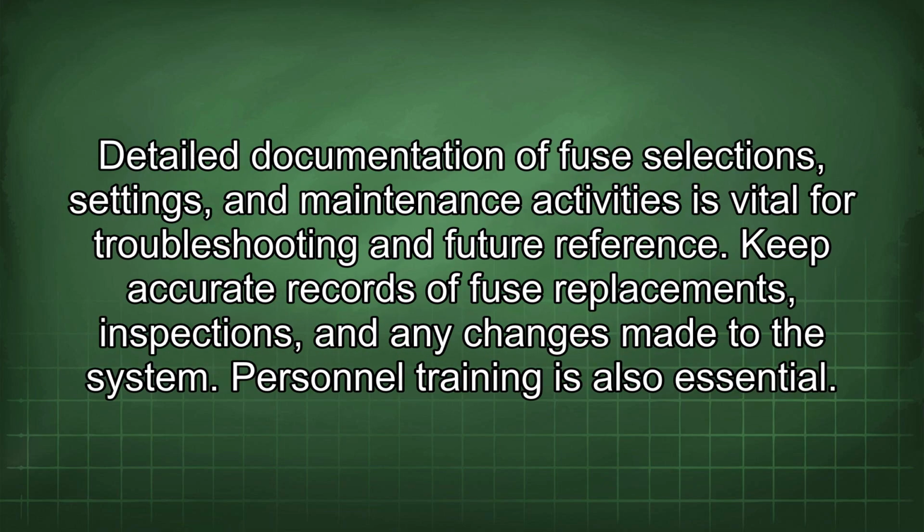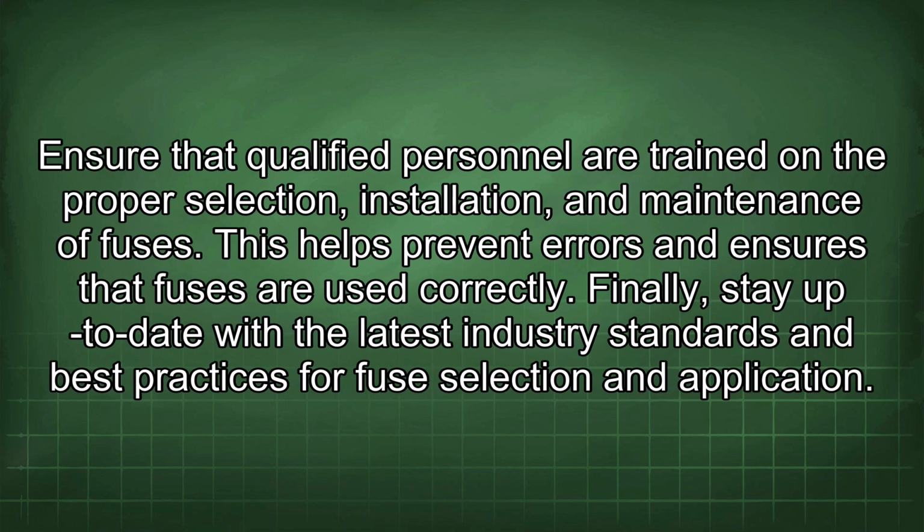Detailed documentation of fuse selections, settings, and maintenance activities is vital for troubleshooting and future reference. Keep accurate records of fuse replacements, inspections, and any changes made to the system. Personnel training is also essential. Ensure that qualified personnel are trained in the proper selection, installation, and maintenance of fuses. This helps prevent errors and ensures that fuses are used correctly.